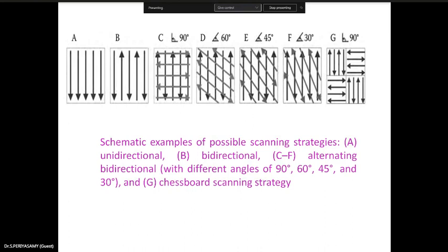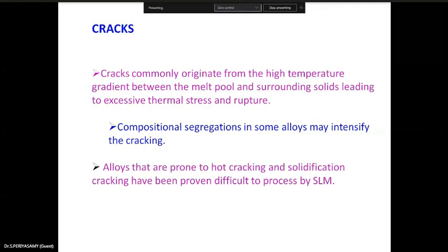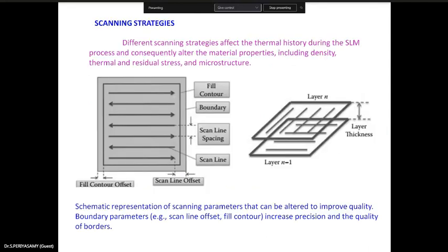So this is a fractionation of the melt pool, or ejection from the melt pool. From the melt pool, it comes out as a separate piece. Separate in the sense that it forms its own shape. It is ready to form a different shape and is not ready to attach with the other things. The fractionation occurs through the surface tension effect. The root cause of the phenomenon is the incomplete melting and fusion of the particles that occurs when process parameters are incorrect, that is, when the energy density is low.